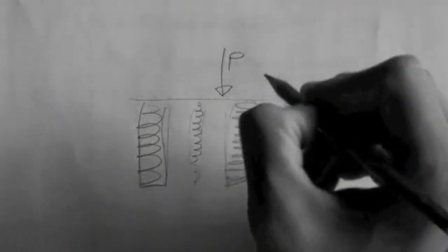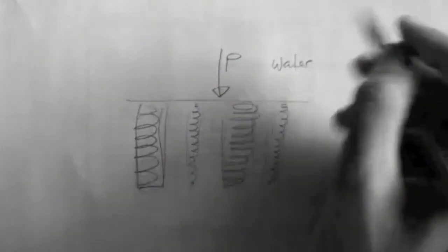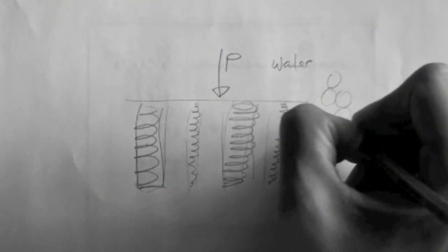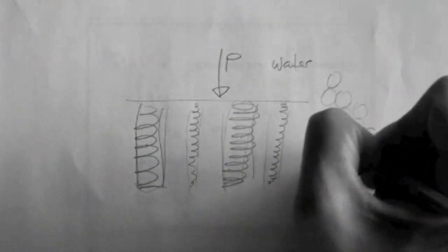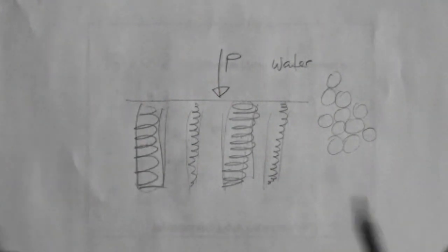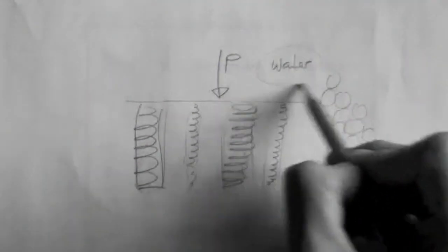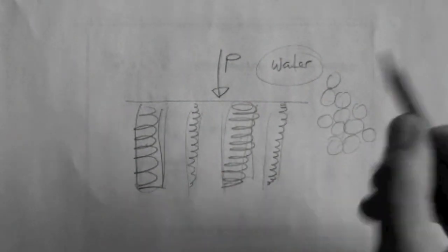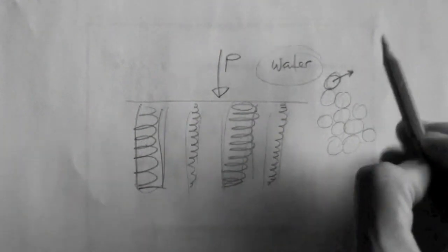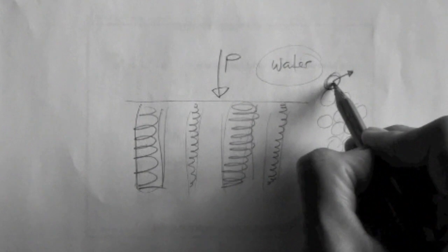Okay? And the water has a higher stiffness than the assemblage of particles. So remember, when we talk about soil, we talk about a structure of particles. That structure of grains that can move relative to each other, that packing has a lower stiffness than water. Now, a particle, the material that makes a particle, like quartz, may actually have a higher stiffness than water. But what matters is not what makes the particle.